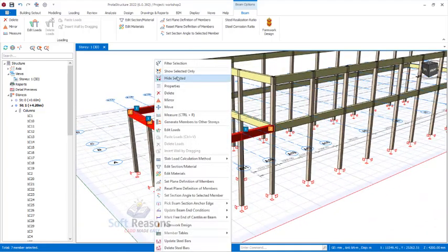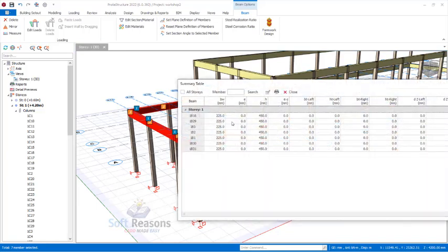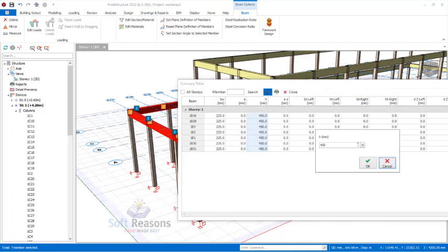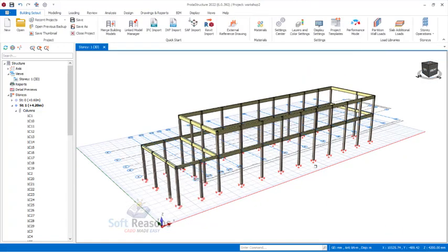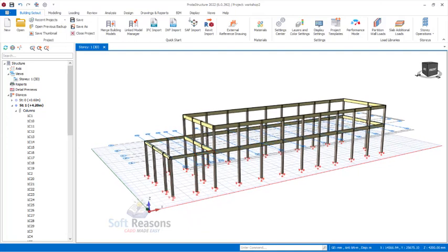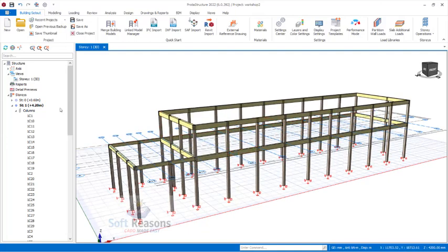So you right click and click on property, and then we have 450 height. Select in this edit provision and click on the column wise edit. In the column wise edit provision, you type 300. I want the depth of the beam to be 300 right there. The same thing applies to the roof beam of the main workshop, so that we can select in the structural 3D provisions.